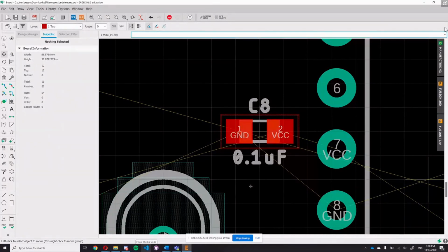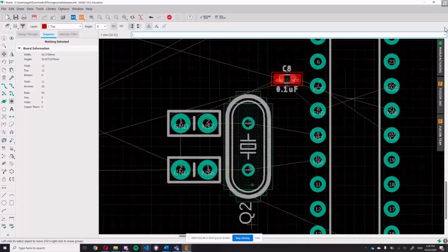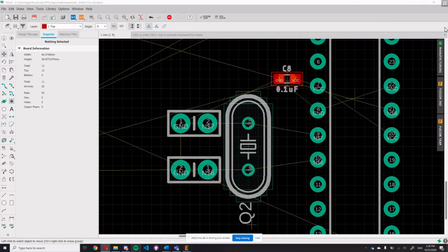I just wanted to add the importance of the line traces of the oscillator. Jakub just placed the oscillator pretty near to the ATmega, because if you draw traces, every trace makes capacitors on its own. You could theoretically do a PCB without components and do traces and loops, so theoretical capacitors occur, and that's prevented by having short trace lengths, so the oscillator can swing well. That's everything I wanted to say. Yeah, thanks for that.